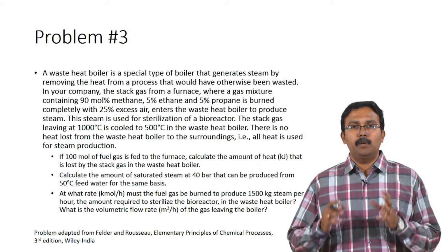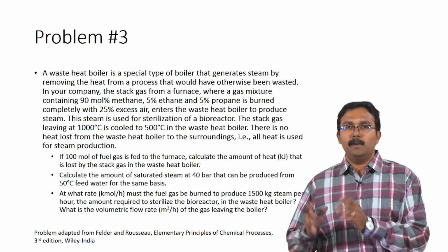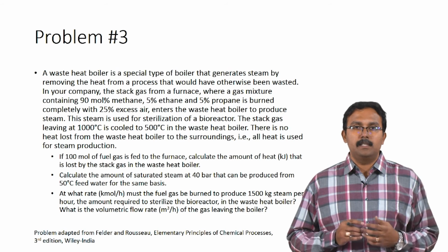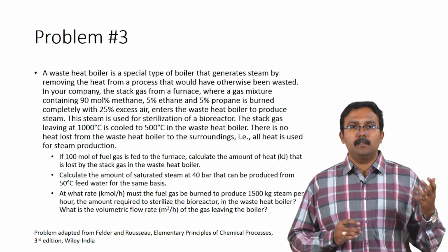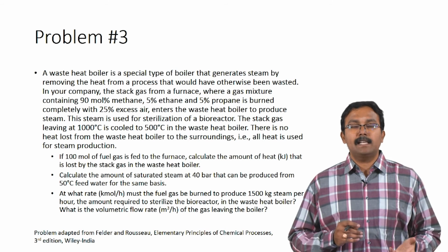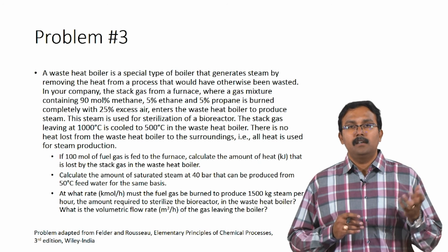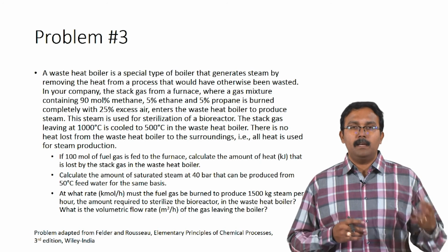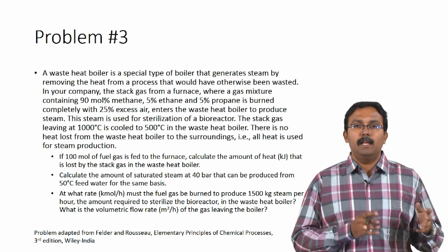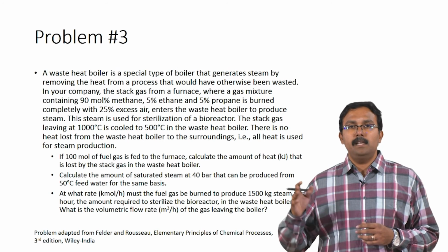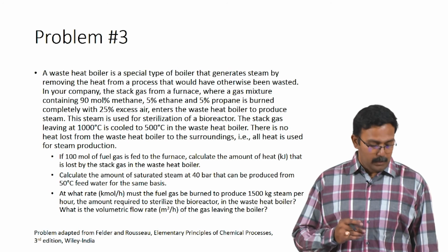So, although we are worried about energy balances only for the waste heat boiler, the feed to the waste heat boiler is from a furnace, and this information is required so that we can have the information about the gases which are present in the gas which is entering the waste heat boiler. So, we first need to perform material balances which will help us identify the composition of the gas which is being fed to the waste heat boiler. So, let us start performing the material balance calculations first.